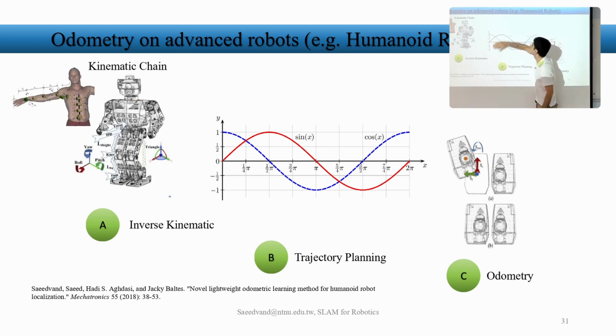Just consider the upper bound. With sine and cosine, you can generate this with a simple function that your inverse kinematics follows. But of course, it's not that easy. You need to do a lot of things on the center of mass. For example, if your robot does this, then of course it falls to the right.